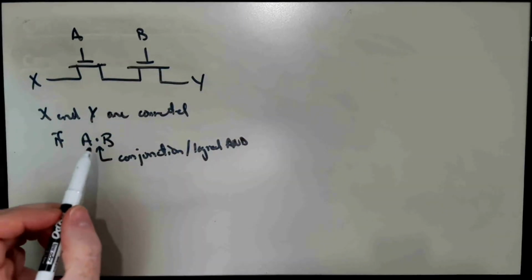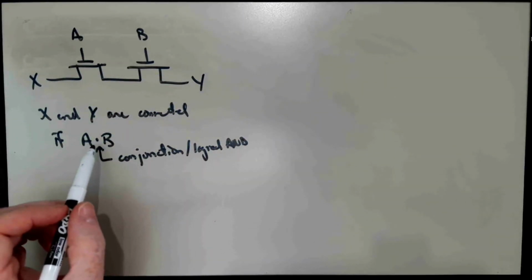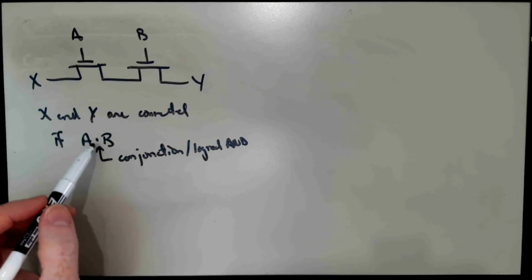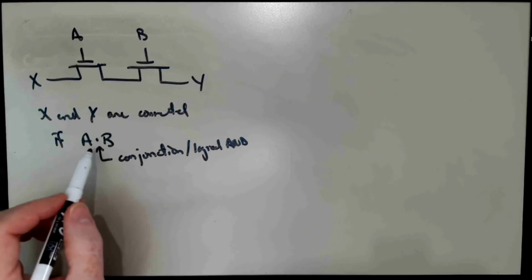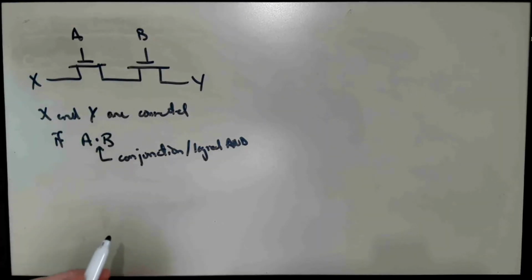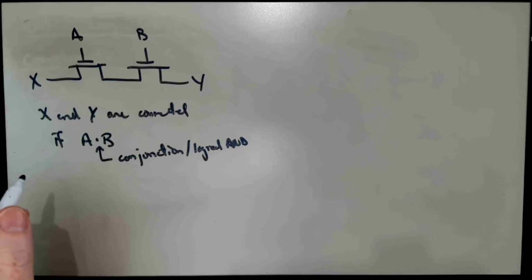And we denote this, again, in this common Boolean algebra notation by multiplication. We won't often put an explicit dot in our Boolean expressions here, but just to let you know, the multiplication, or just the juxtaposition of A and B, corresponds to logical and in our notation. So we have parallel corresponding to or, and series corresponding to and.